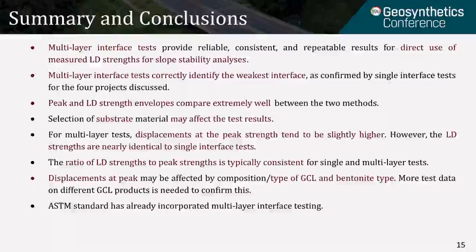In summary, multi-layer interface tests provide reliable, consistent, and repeatable results for direct use of measured large displacement strengths for slope stability analysis. Multi-layer interface tests correctly identify the weakest interface as confirmed by single interface tests. Peak and large displacement strength envelopes compare extremely well between the two methods.